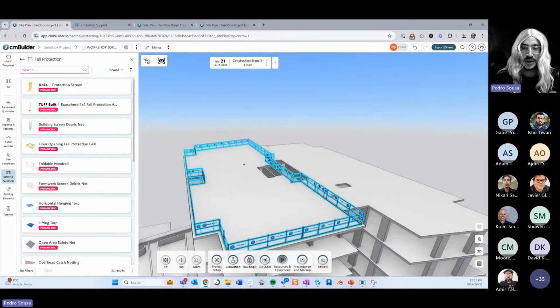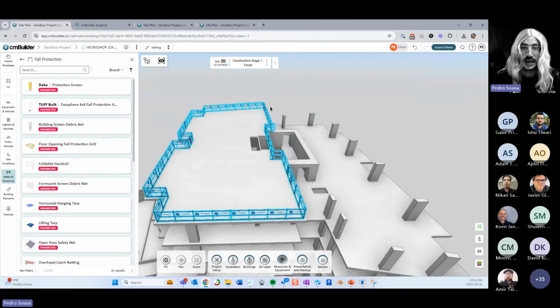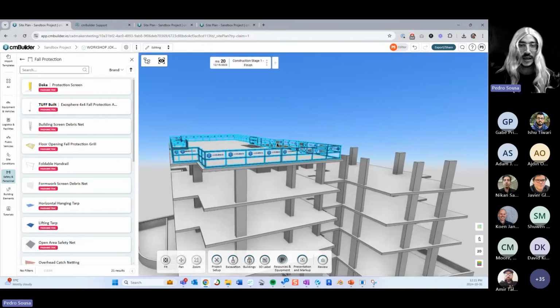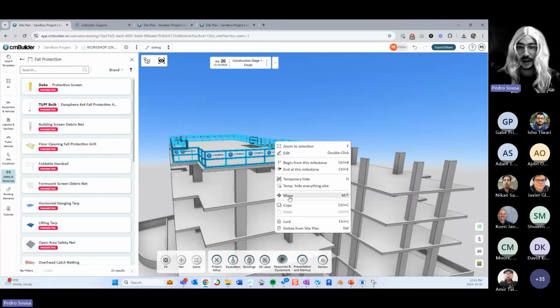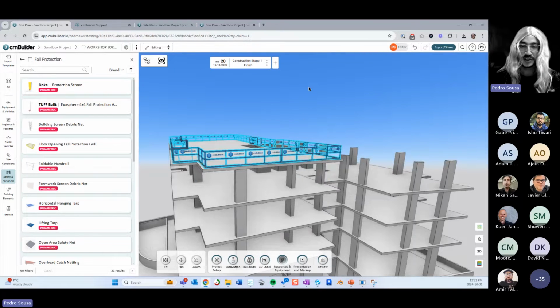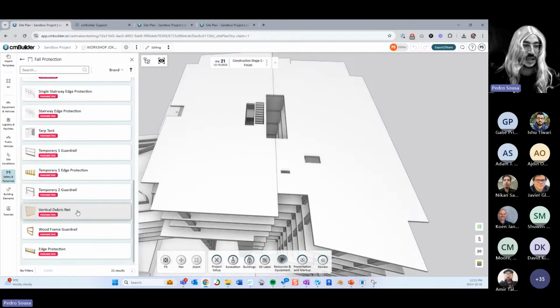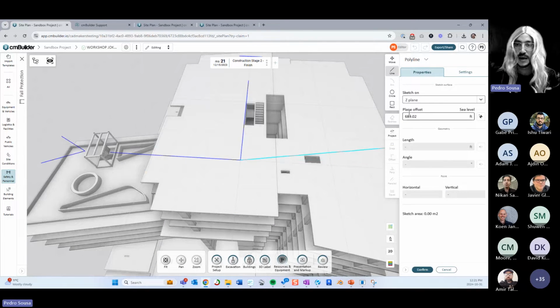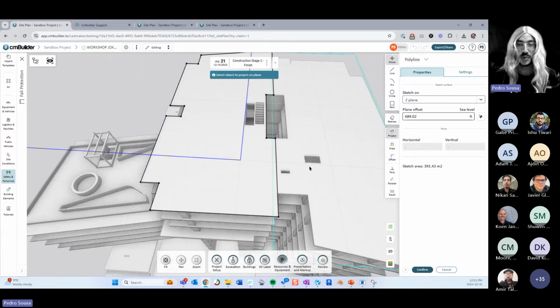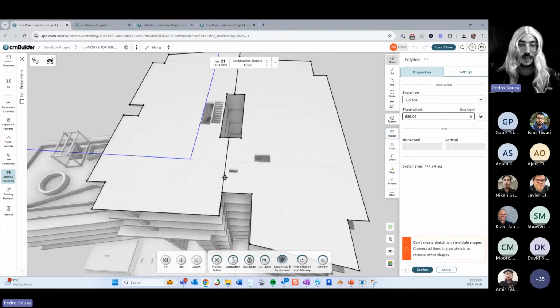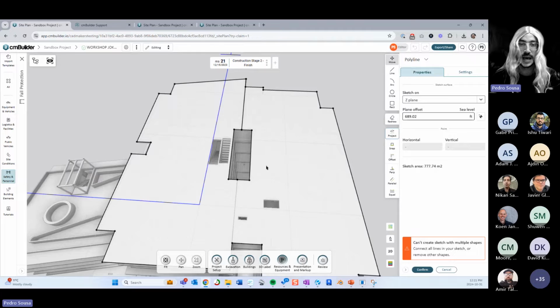So this slab protection, you can either create in this middle part separated from the rest, or I can simply interrupt this slab protection at this stage. And when I go to the next stage, I will go ahead and do the same slab protection in here. I'm going to project the shape of both slabs, and I'm going to go ahead and delete these items over here in the middle.